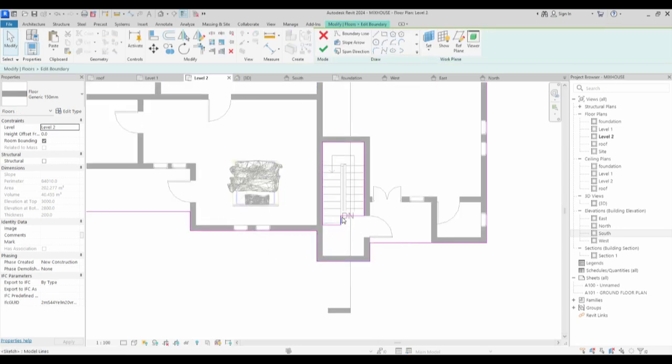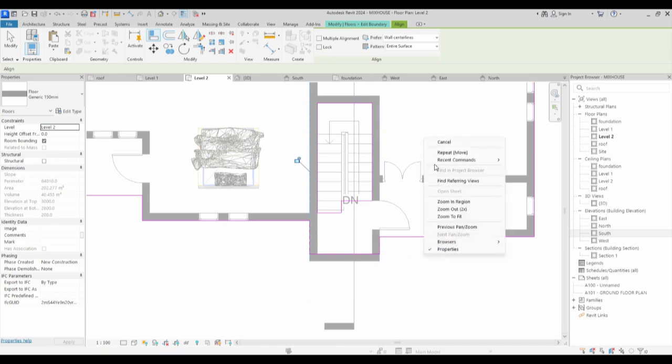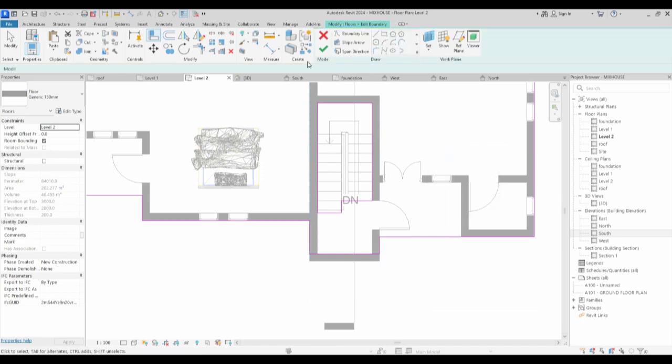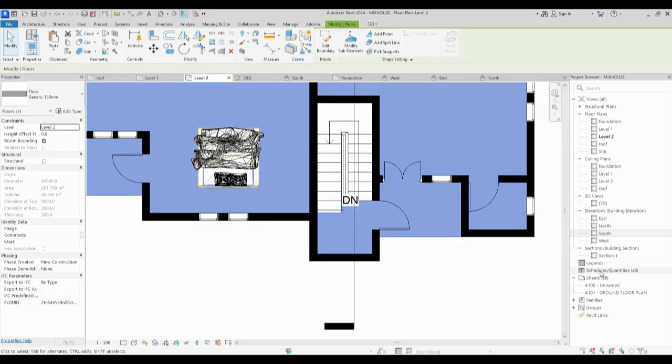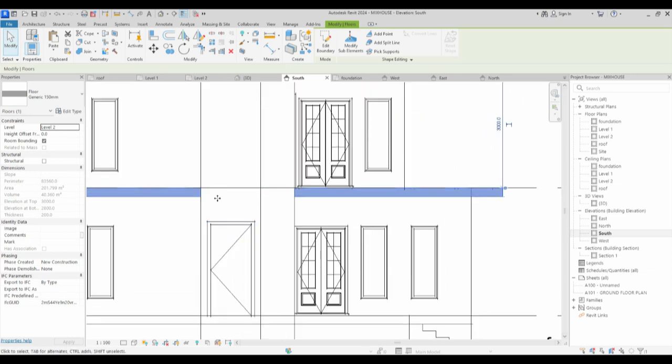I have the slab which is here and this is normal, but I'm going to land here and move inside, but I don't want to see the slab from outside the wall. So I pick it and set it inside so that it goes within this space. Because this is construction, anything can happen. You do that from here. Click finish. Then go to the elevation, start elevation, and extend this so it's joined together.